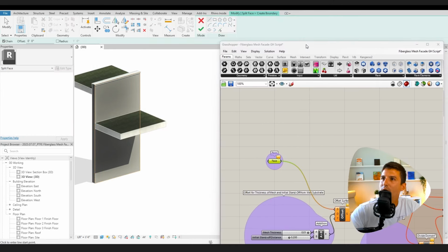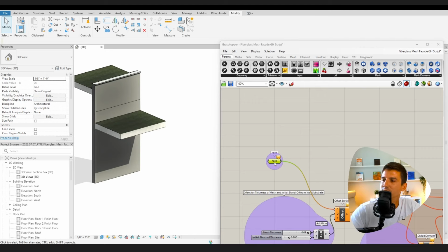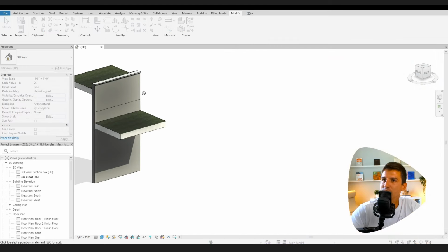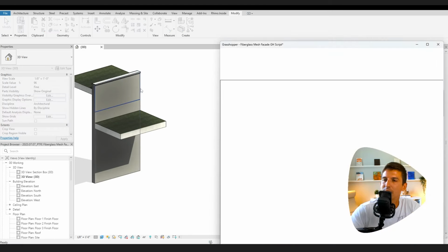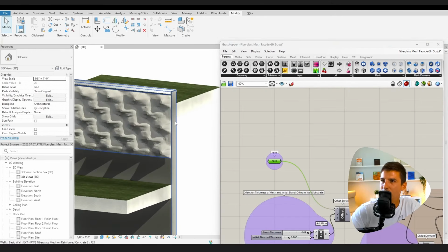And if I want to, I can do a pick lines command and use an offset. So here, let's say I want it to be maybe 10 feet down from the top edge, or I can go in and draw the face myself, right? As long as I'm drawing it from yellow line or orange line to orange line, or is that yellow? I can't really tell. And then you can check that off. This should be two different faces here. Let's see if that worked. So I'm going to go and say set one face. Yeah, there's the top face. So I'm going to click on that. That's how you really can have a lot of control in Revit on where this lands.